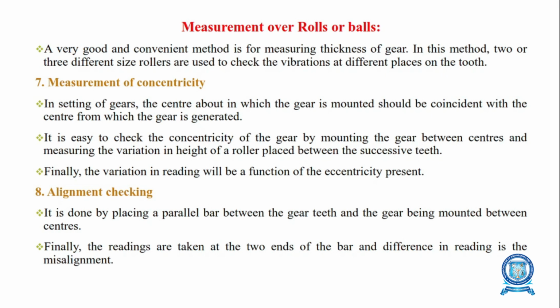Here, measurement over the rollers placed in the space between a pair of gear teeth gives a convenient method for checking tooth spacing and pitch diameter. Two or three different size rollers are used to check the variations at several places on the tooth.